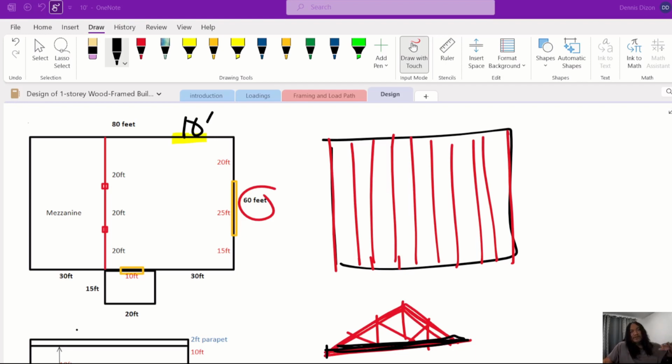And also, when you link the load, you can find which one you are linking. So in MB01, this is the one with one end supported by a built-up post and the other end by a first standing column. If you remember, the 20 feet here will be to the center of the column.